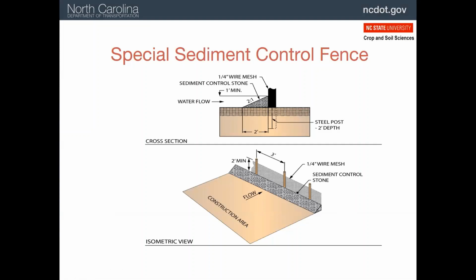The construction of this device is simple but effective. T-posts are installed 3 feet apart. Hardware cloth is attached to them. A 24 gauge galvanized metal material with 1/4 inch openings is what we're referring to with the hardware cloth. It should be that 4-foot roll we talked about earlier with the outlet, folded in half so there's 2 feet on the ground, 2 feet going up the posts, and you put washed 57 gravel on the hardware cloth to a depth of at least 1 foot.